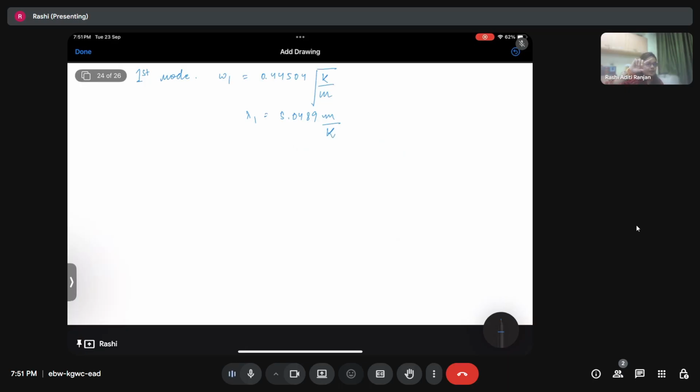If you remember, in the previous question, we used A minus lambda I into x is equal to 0, because that is what eigenvalues satisfy, and the eigenvectors are nothing but the mode shapes. Likewise, we are going to do it over here also. What we did was we wrote the determinant of lambda I minus D is equal to 0. So lambda I minus D into x is going to be 0.